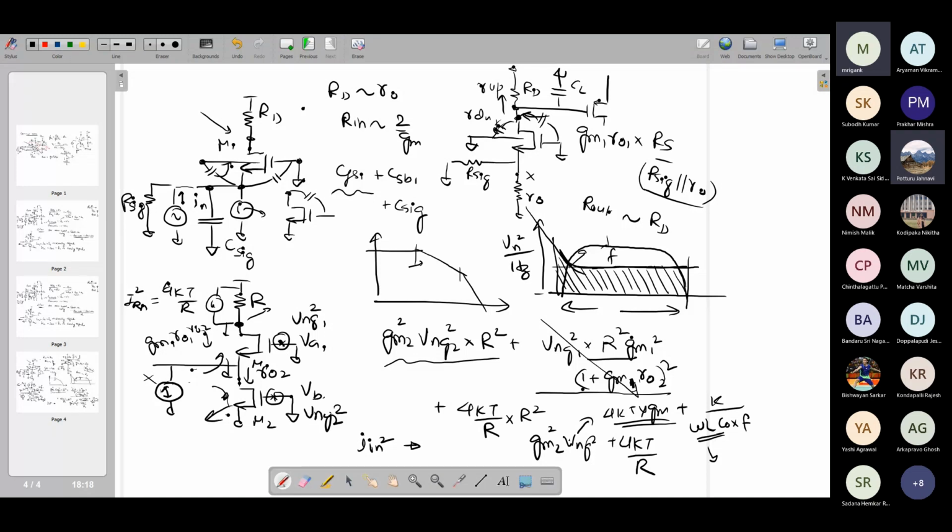Whenever we are talking about noise comparison with the input signal, we will have to integrate and find out the net noise voltage, the RMS noise voltage, at the input. Both quantities you will find in the literature or in a particular design statement. You may look at the Vn squared per hertz curve, or you will get the integrated noise, which is the RMS value of the noise obtained by integrating the input referred noise spectrum with respect to frequency over the desired bandwidth.